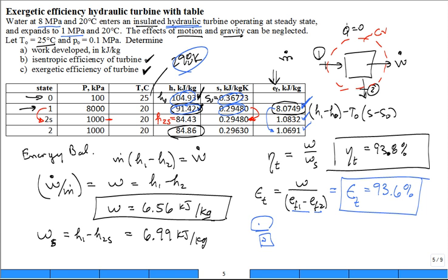And I'm bringing in heat from a high temperature, QH, and I'm rejecting some heat at QC. And then you ask yourself, what is the thermal efficiency of that Carnot heat engine? And you come up with about 43% or something. And then you report it. And every now and then you'll hear this out in the news. They'll say, these engineers are so stupid that the maximum efficiency they can get out of a power plant is like 43%. Well, theoretically, the Carnot, with that high temperature here and that low temperature here, may be limited to 43%.